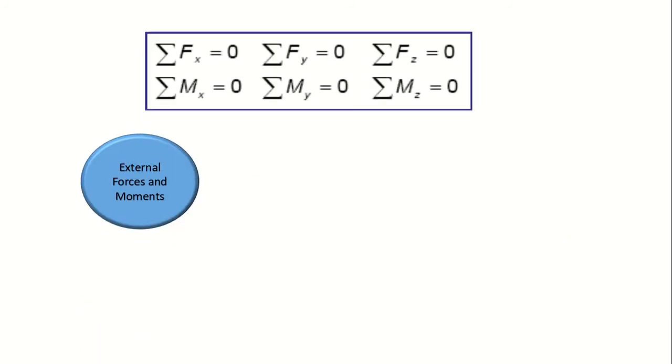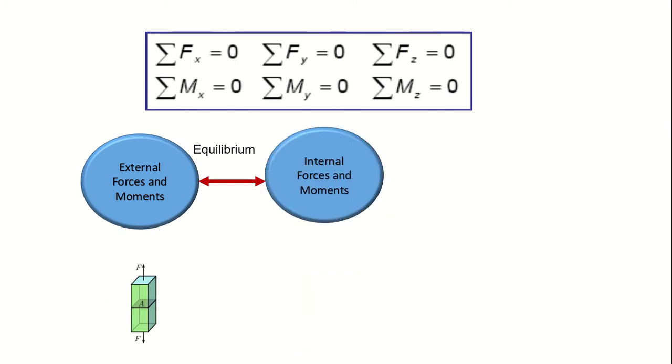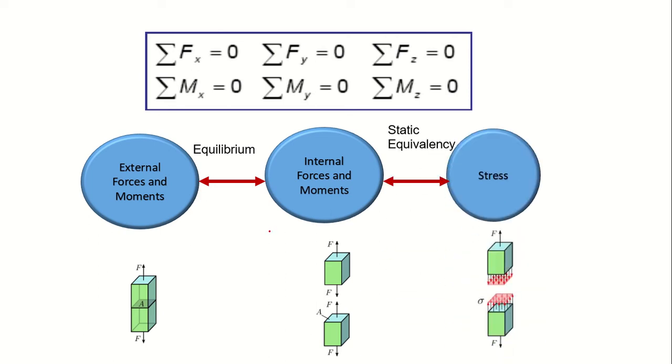Next, how is stress induced? Imagine a body is there. For this, we apply an external force. Then, due to the equilibrium condition, internal forces or moments will develop. Then the stress will be induced at the corresponding cross-sectional area. You can call this a normal stress. The normal stress is given by the unit force per perpendicular cross-sectional area.